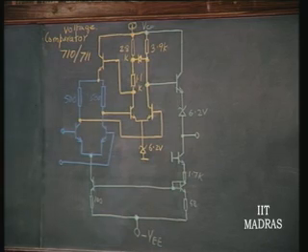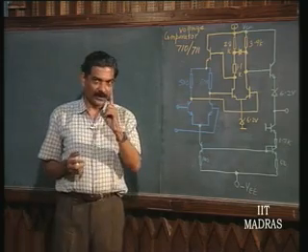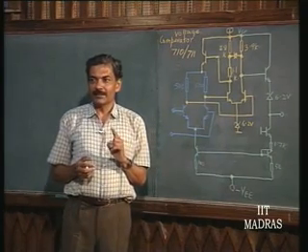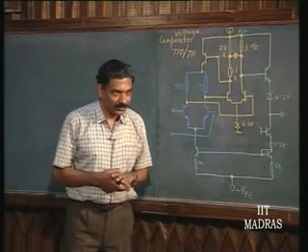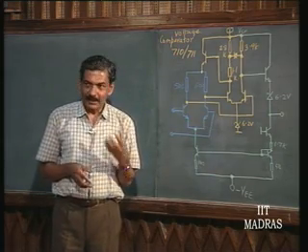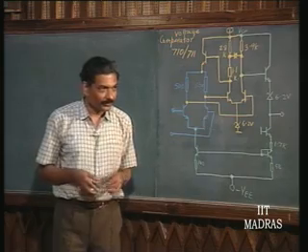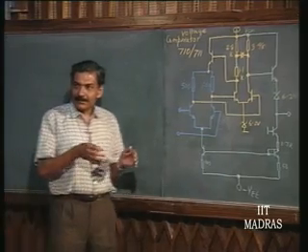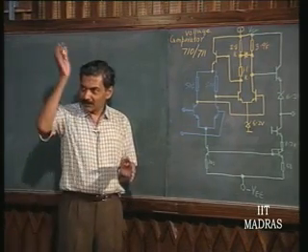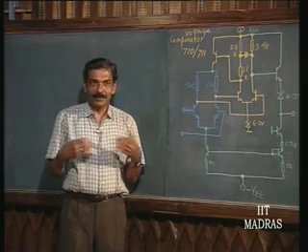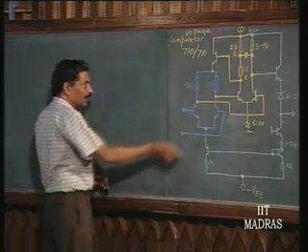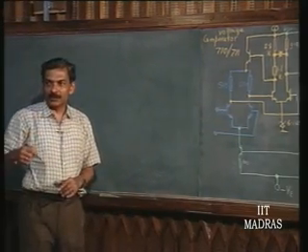That need not be a botheration as far as you are concerned, because we can adopt positive feedback in order to boost up the gain here. Now, this is an important point. Nowhere in application of amplifiers do we use positive feedback, because it is highly sensitive. Gain becomes then more sensitive to active parameters than before. But here we do not bother about sensitivity. It is not likely to stay in active mode for long, it is going to quickly go through that. During that time, gain has to be kept as high as possible. The specific value of gain is not going to matter. So, you will see that positive feedback is used in order to boost up the gain.